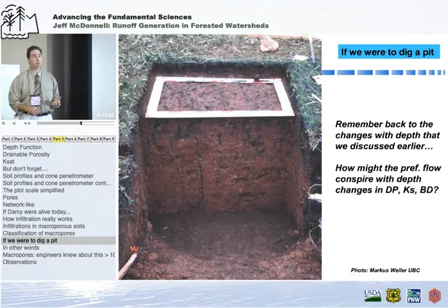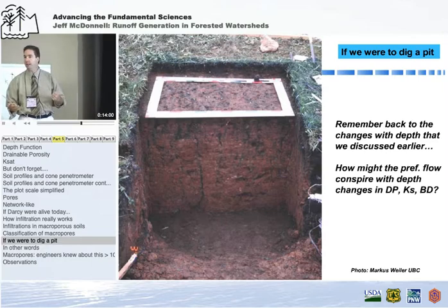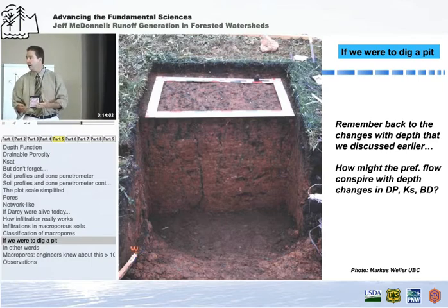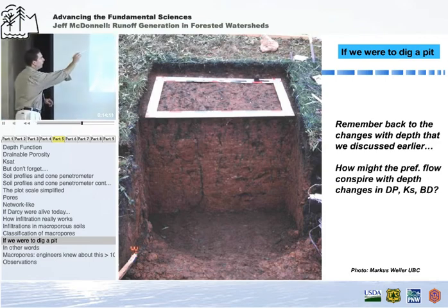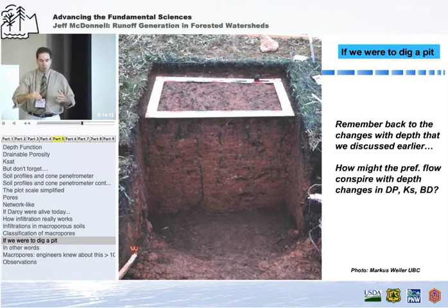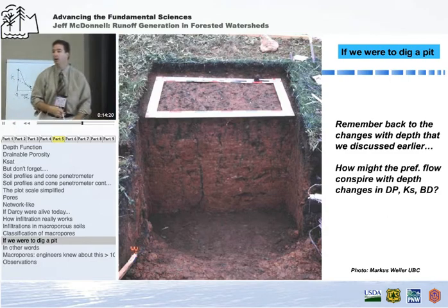It also presents a problem for how we measure things. When we go out to forested catchments and use tensiometers, TDR rods, any kind of point measurement when we're inserting something into the soil and making a measure, we need to be very aware that where we input our point measurement device, really what it's representing. And it may not be representing the mobile water that we want to sample.